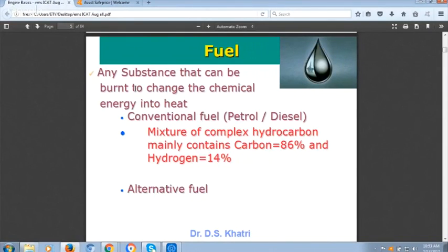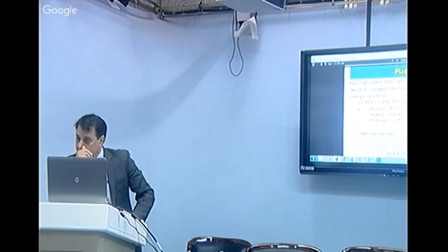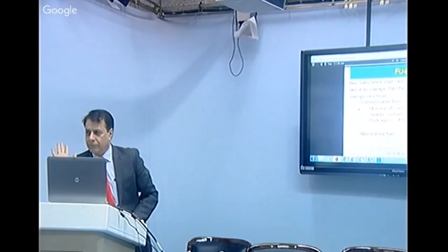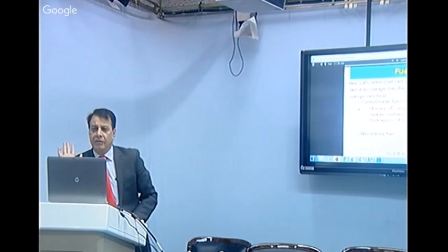Excuse me, sir. Yes, please. Sir, can you please explain volumetric efficiency? Volumetric efficiency is the mass of the air which the engine is actually taking, divided by the mass of the air which the engine can take theoretically. So it is the mass of the actual air divided by the mass of the theoretical air. Okay.